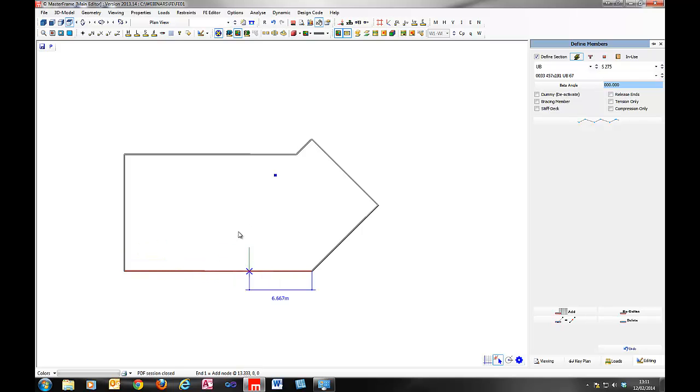Again, I want to split this. I'm actually going to model two finite element surfaces on this because I do want to model a construction joint halfway through it, so that I don't have moment transfer between one part of the slab to the other. So we're going to do that, and I'm going to introduce that join at a distance of, we can say it's 12.5 meters from that end, snapping in and going up and orthogonally snapping up here like so.